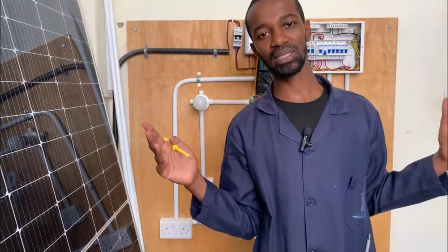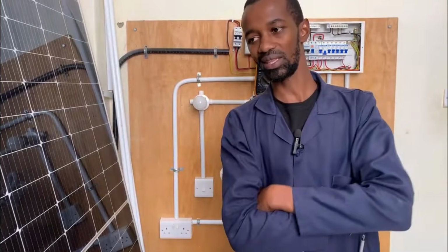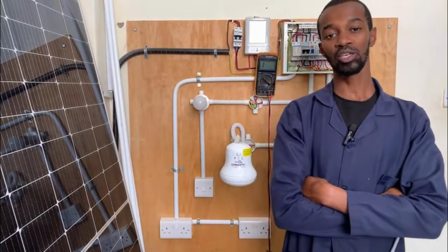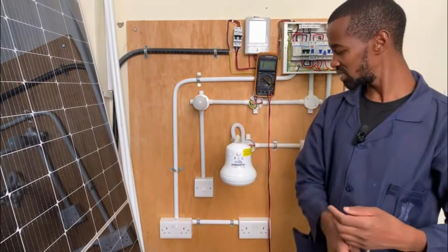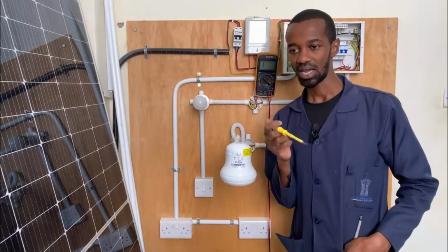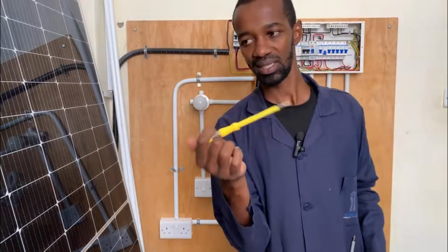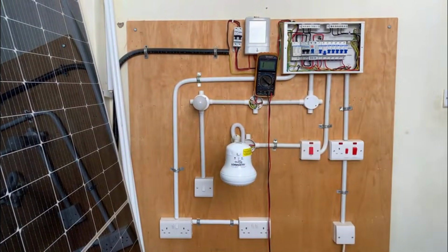For instance, this switch here, you will definitely know that there is an open circuit. This normally happens when there is a loose connection, especially on the phase or the line. A loose connection on the neutral manifests itself in this manner. There is a return voltage or current that, when you place that tester on the neutral, you will be able to experience it.